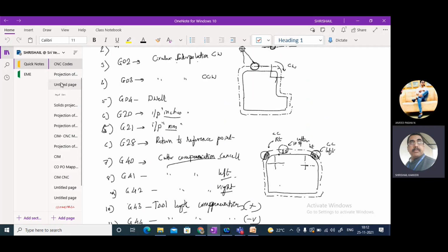Of course, if it is parallel to the axis of the arbor, then a line will be in contact, but it will not happen. So it will be in a spiral shape, so that at one time the whole load will not be acting on the cutting tool. Correct, no? If you have the tool like this, this portion of the tool is engaged, and when it rotates, the next portion. So at one time, the whole tool will not be engaged in the cutting.